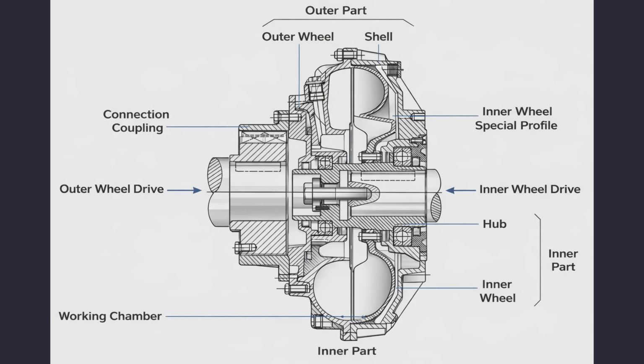So to mechanically handle this, one of the good ways is to use a coupling. Out of the many couplings available, one of the most practically usable is called a fluid coupling, which is nothing but a hydraulic coupling by itself. For anybody who does not know much about this type of coupling, there is really no physical connection between the input and output.